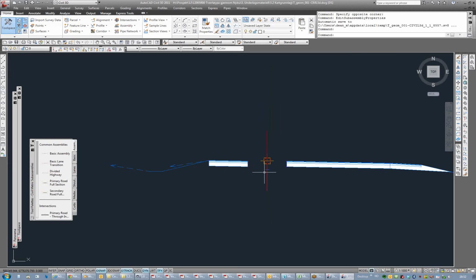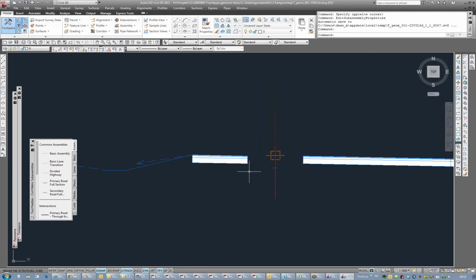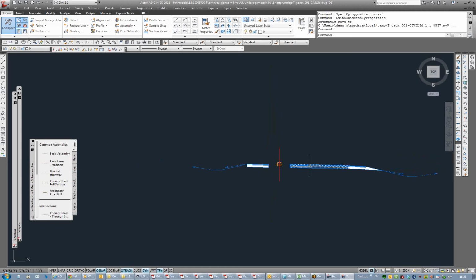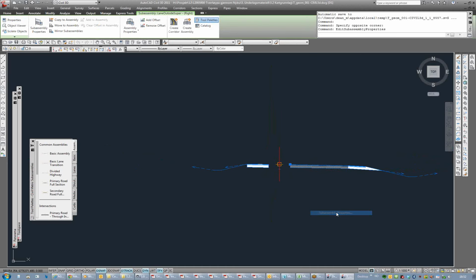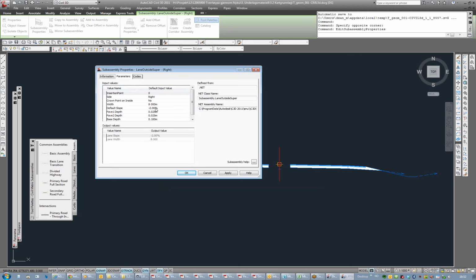So. Okay. Now do the same thing on the right side. Okay, this is going to be 3. 3. And 2%. Just delete the minus sign. And even though it says pavement, we can change the material to grass in the codes. Okay.